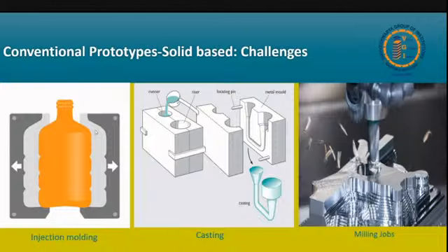And also, you cannot change any design. For the first part you make the mold, and then if you think you have to change the design a little bit, you will have to make a whole new mold. So for iterative designs and in the development process, injection molding is not very suitable. It is basically for volume runs, where you need thousands of parts and your design is finalized. Then we go to injection molding, because the per part cost is very low.